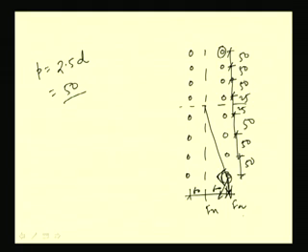So, this rivet will be the critical rivet, either this one or this one. So, we will calculate the force exerted on these rivets and then we will see whether it is exceeding the rivet value or not, and accordingly we will check the design. So, for calculating all these things we have to know R1, R2, R3. So, let us find out R1.